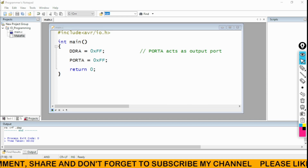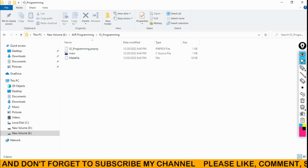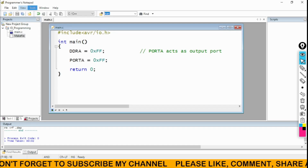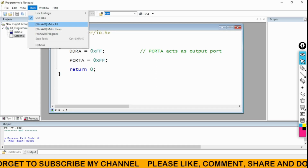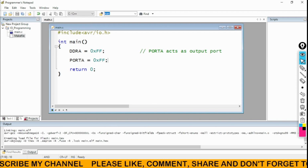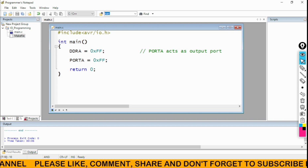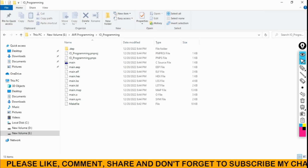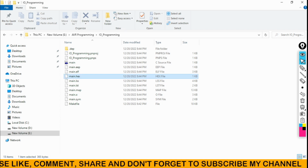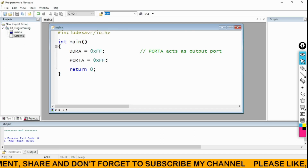Okay, so we'll go into the folder, what is done, main, makefile, IO programming. Then I am going to go into Notepad, make. You will see here, after making all, you will get the message process exit code 0. You will see in that folder there are several files, where the main.hex file is important. So to run this program, we require Proteus software.